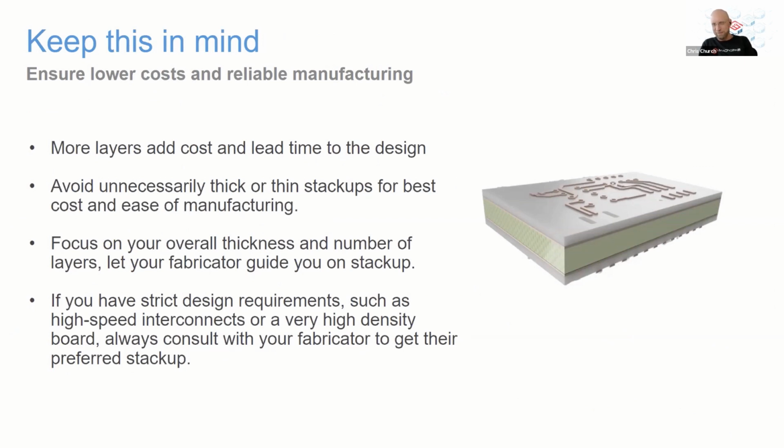I don't know how many times I've had people reach out to me and say, hey, I've got this 16 layer board with micro vias and blind and buried vias. Can I get 100 of those in 3 days? No, absolutely not. You're looking at a minimum of a couple weeks because it's a very complicated process with a lot of fallout. The next thing here is, again, avoid unnecessarily thick or thin stack ups. It's just going to make your manufacturing easier and lower cost.